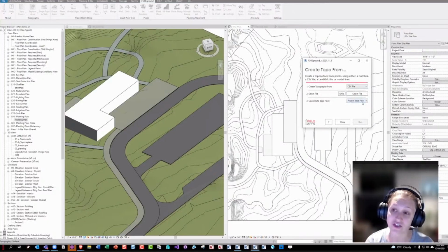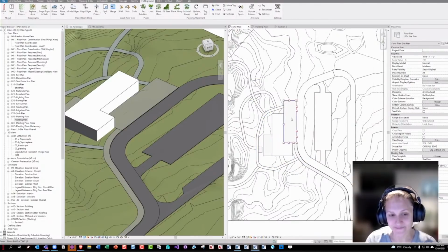It still just generates points and makes the topography from those points, because that's how topography works in Revit. There's nothing we can do on the back end that changes how topography works ultimately. Points are points and topo's topo. We're hopeful that based on the Revit roadmap there might be some new things coming out of the dev team, but for now, topography is topography.